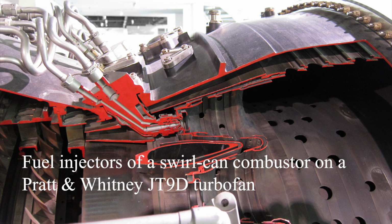The fuel injector is responsible for introducing fuel to the combustion zone and, along with the swirler, is responsible for mixing the fuel and air. There are four primary types of fuel injectors: pressure atomizing, air blast, vaporizing, and pre-mix or pre-vaporizing injectors. Pressure atomizing fuel injectors rely on high fuel pressures, as much as 500 psi, to atomize the fuel.